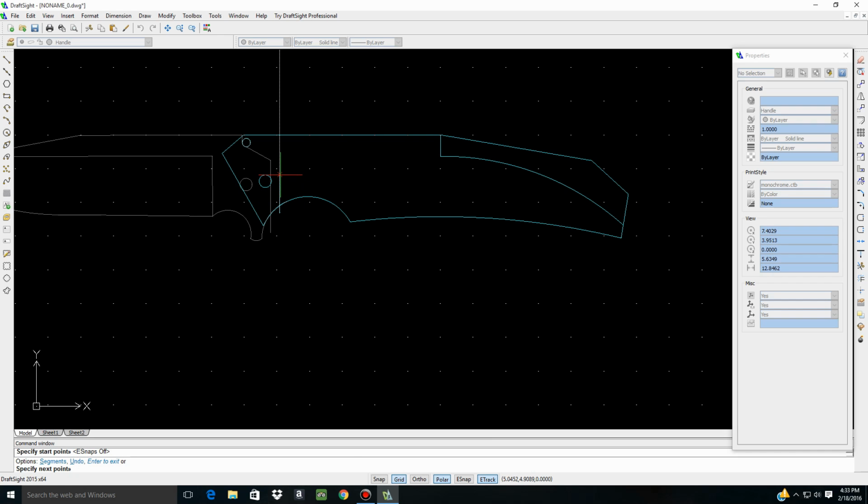Okay. We're going to snap a line right about there. As you can see, it's perfectly straight up and down. You definitely want that. We're going to bring it back, your typical lock bar. You don't want to go super long. Don't go way back here with your lock bar. It's going to be way too flexible. And don't make a 1-inch lock bar, because it's going to be really hard to operate. So you want to get right about there. Looks good. We'll click there, and we'll drag it down. And you could overshoot. That's no big deal.